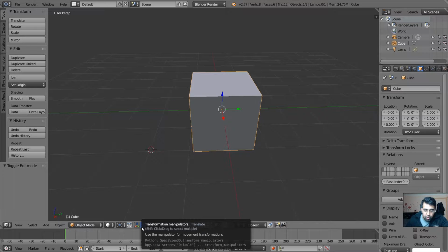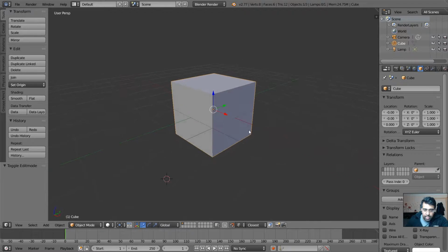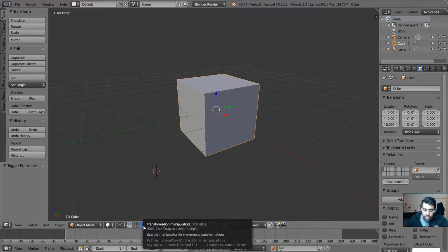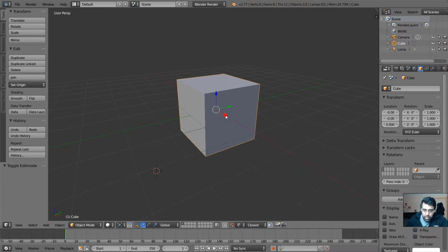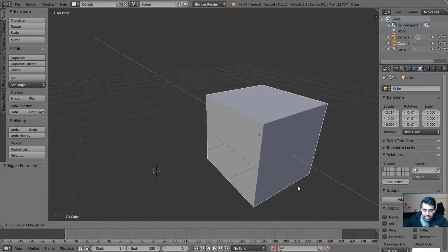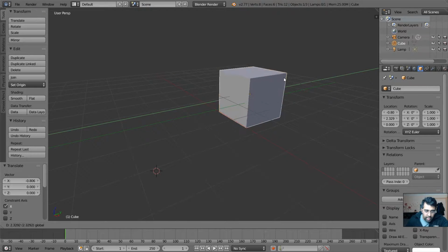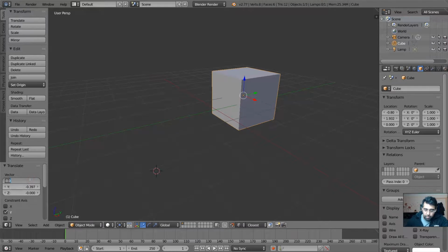We've got our gizmo transform manipulation. Let's say I click here, turn it on, and then I've got this gizmo there, right? So this is right now on the move gizmo. I click here, I can click on this red, and then I can move it on the x-axis. If I want to move it towards the y-axis, on the left you can see the values changing as well. So if I click here on the y-axis and leave it here, now these values have changed. So I'm going to bring them back by typing 0, 0, 0.